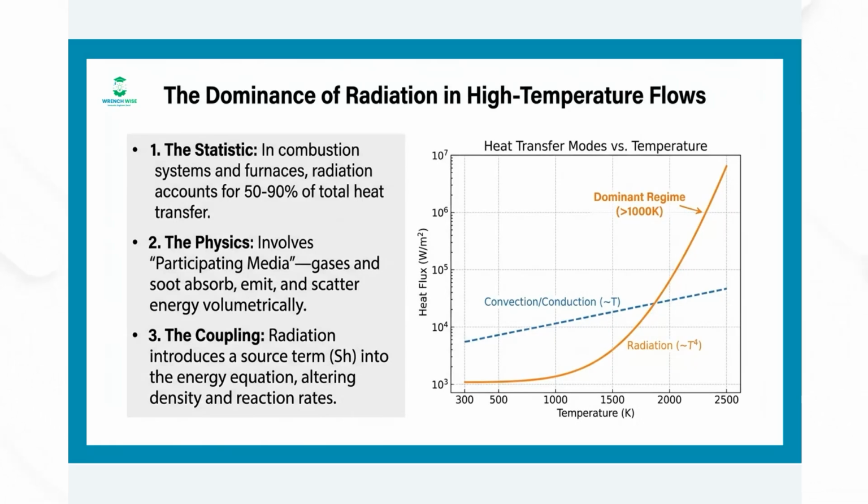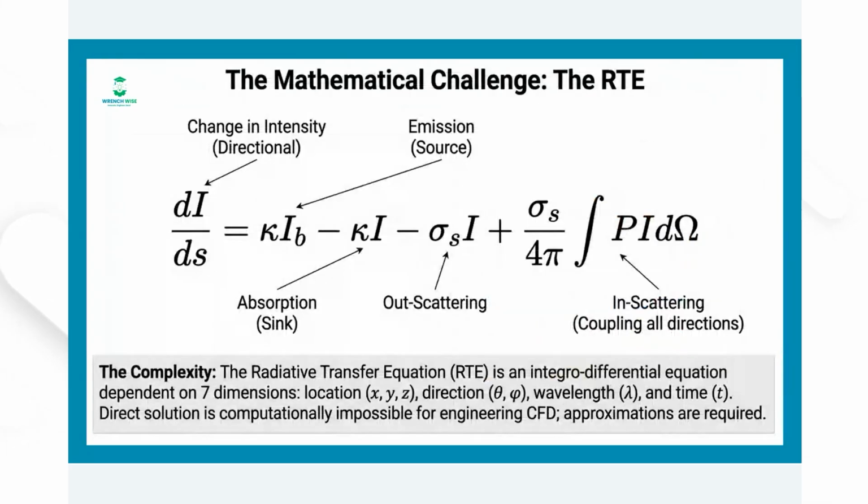So this makes CFD simulations quite difficult because of coupling, because radiation introduces a massive source term into your energy equation. This alters the fluid temperature, which alters the density, which changes your buoyancy and the flow speeds, and the whole circle sort of keeps going there.